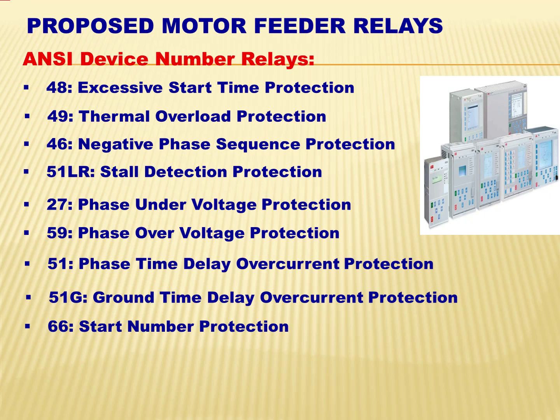Repeated starting of a motor in close succession will cause the accumulation of heat in the conductors and body of the motor. To safeguard against damage, it is desirable to limit the number of starting attempts that are made in a predetermined time period.